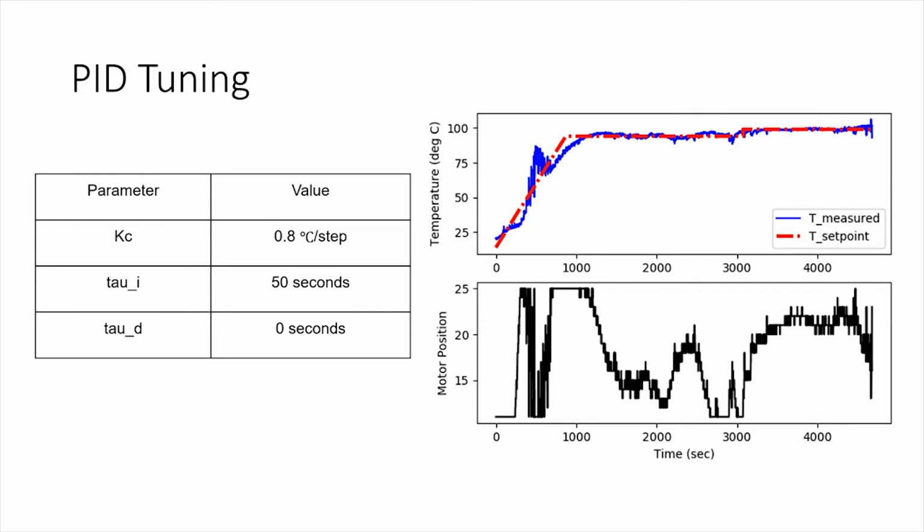We also implemented an anti-reset windup loop to stop our integral term from accumulating when our stove knob was maxed out because it couldn't generate any more flame size, and also while it was at a minimum so that we didn't extinguish the flame on the stovetop.